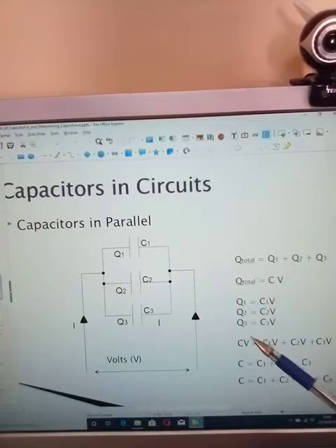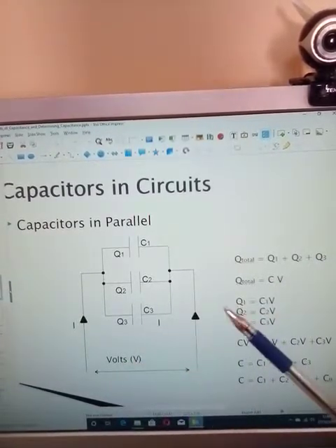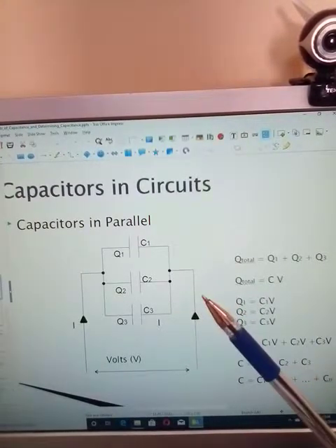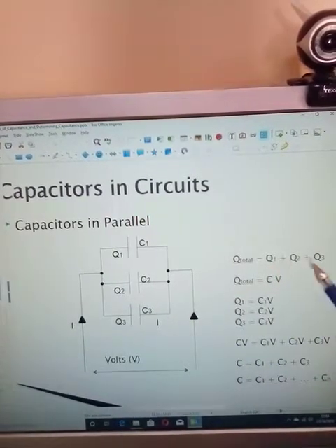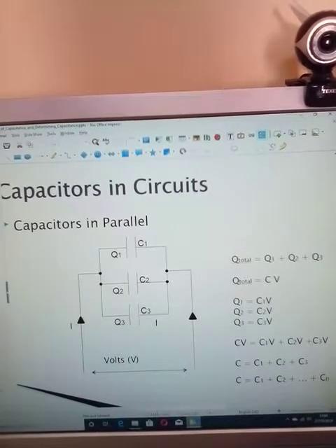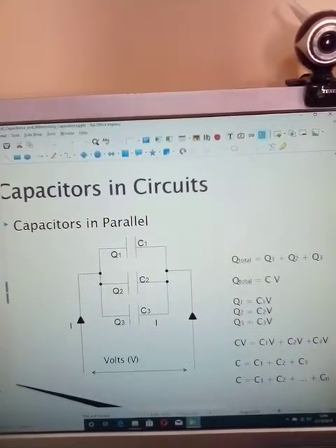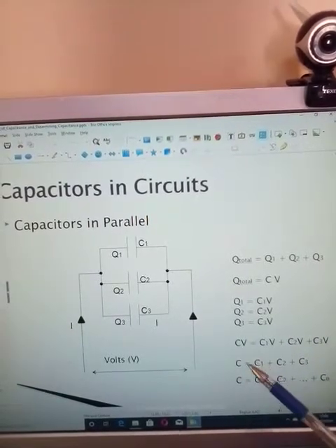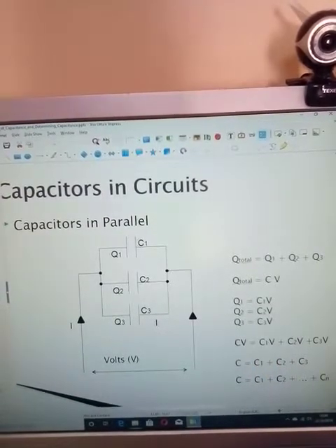they're simply added. Now remember that in respect of resistors, there is a difference in regards to resistors and capacitors. Capacitors in parallel are added as resistors would be in series, but resistors in parallel would have your 1 over ratio, okay, or you have your reciprocal. And this is just the charge in regards to volt charge across the capacitance.